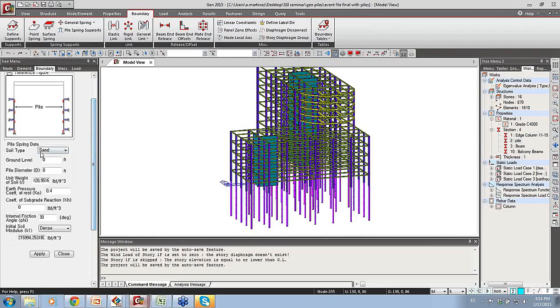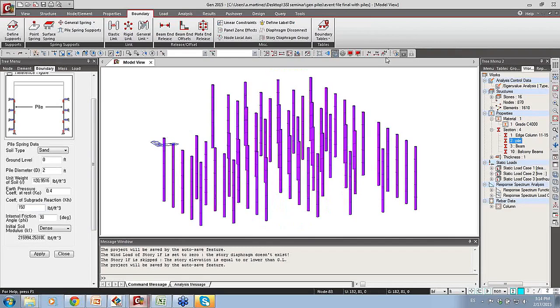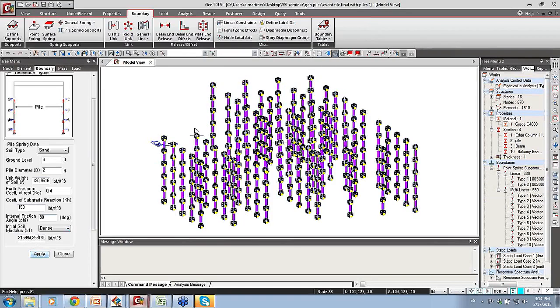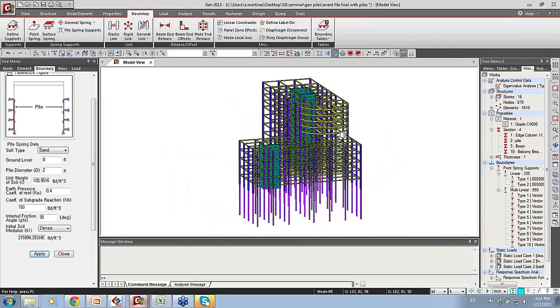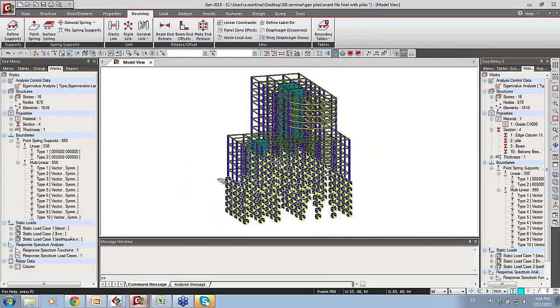And then we see here that very easily, like I was mentioning, I know the diameter of my piles is 2 feet. I choose a soil type that will choose a different PY curve depending on what I choose. And then I just input some value for the modulus of subgrade reaction, and then I apply them directly to my piles. So for that, I can isolate my piles. I have different sections here in the table, and I could just tell it to only activate those. I can then select everything that's shown and apply these soil springs, and we see here now that they've visually been confirmed and activated. So then I can just reactivate everything and run the analysis, depending on some other steps, like adding maybe a response spectrum or a time history.